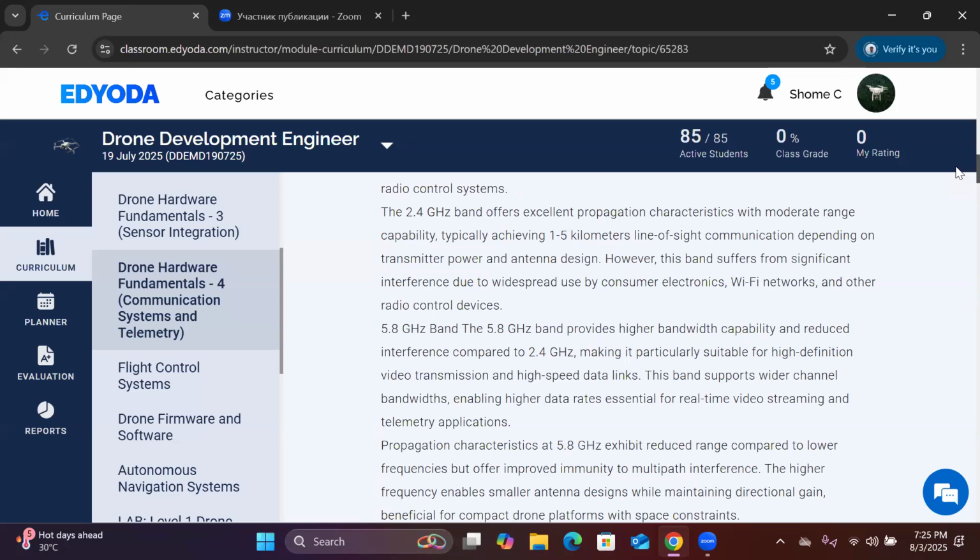I need to add an RF power amplifier after the wireless LAN module to increase my RF power capability. So how to do that? For that, we need to do a cascading of several power amplifiers. We need to use a pre-amplifier. We need to use a final amplifier. So like that, we need to cascade the power amplifier modules because every RF power amplifier will have different gain blocks. So we need to add the different gain blocks. We need to add up the gain. We need to check the linear region of the power amplifier. We need to check the 1 dB compression point of the power amplifier.